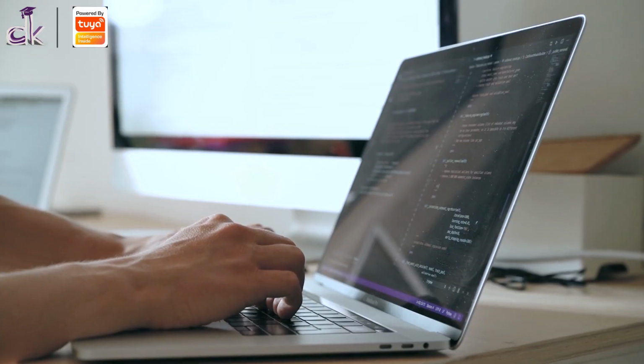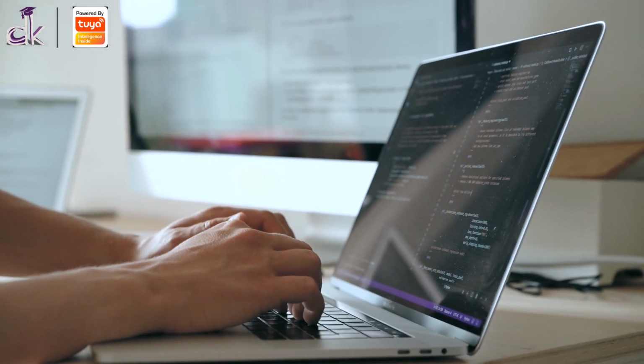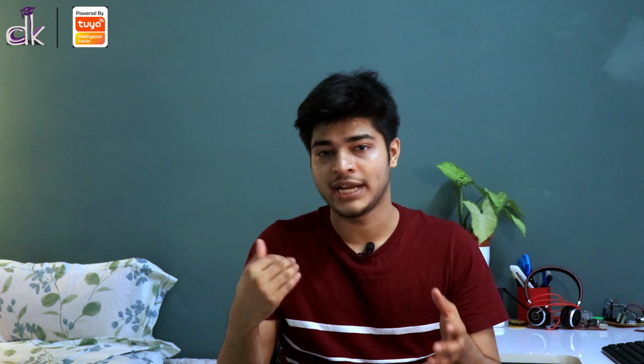Now, the second thing that you need to consider is code development. You need to write firmware on the device that will take certain actions based on commands which will come either from the cloud or from the app. For that, you'll need to write your own firmware. And secondly, in the firmware, you'll need to think about how to do over-the-air updates whenever there's a new bug or whenever you want to push updates. So that is the second aspect, which is code development.